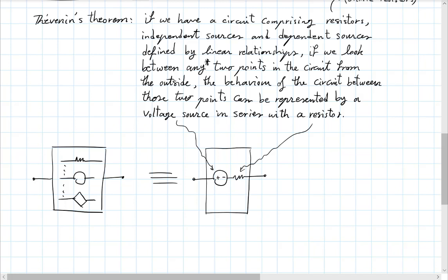Yeah. So that's one very good insight. You're saying, well, a resistor takes care of the slope of a curve. If you're thinking about a curve or a graph, voltage versus current, an IV characteristic, with one resistor you can represent any slope. And with one source you can shift that line with whatever slope. You can shift it up and down wherever you want.